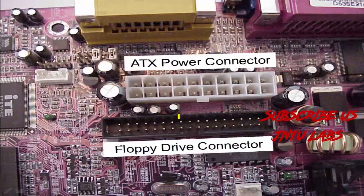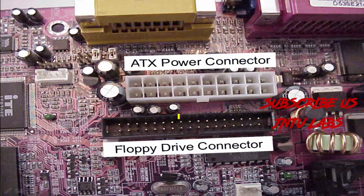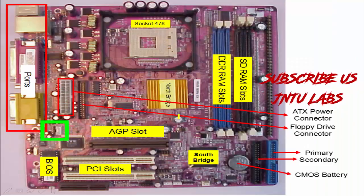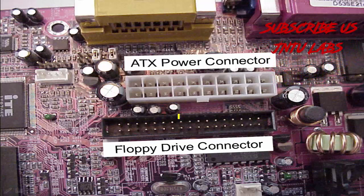Then the ATX power connection and floppy connection. The ATX power connection is used for power supply of the motherboard. To get power supply to the motherboard, this ATX power connection is used. If your motherboard is not turned on, or if you are not getting any lights from this motherboard, then you can see that your SMPS is having some problem, so that you can't drive this motherboard.